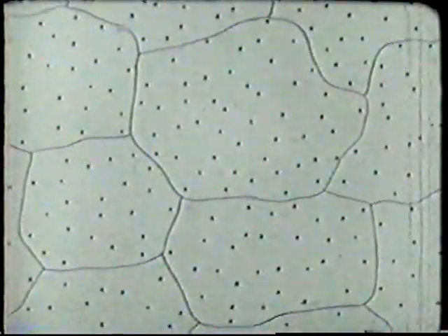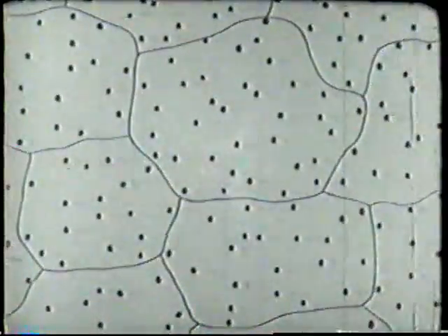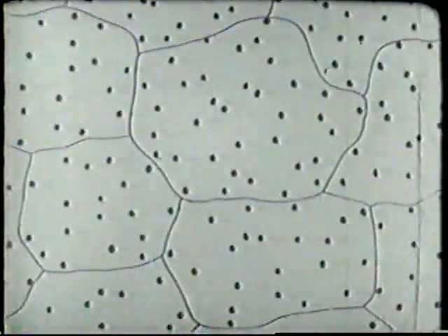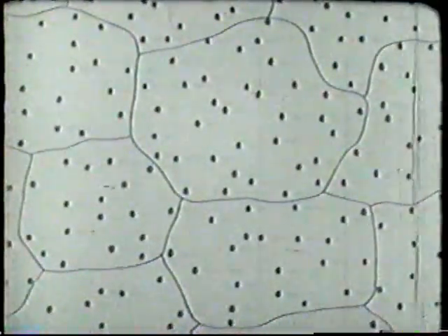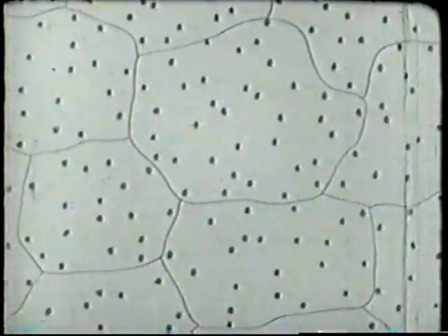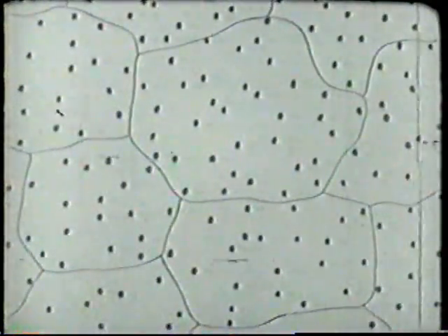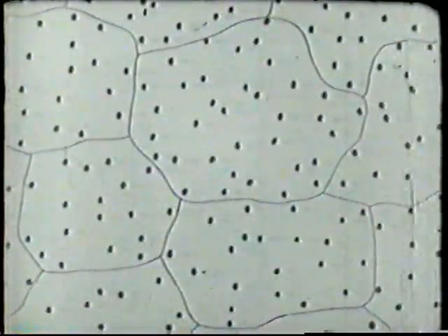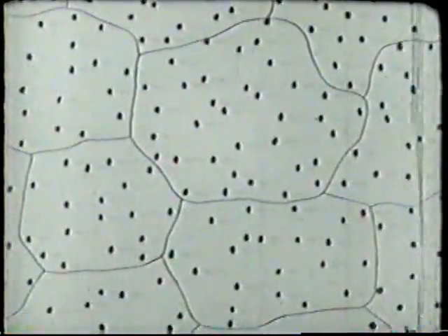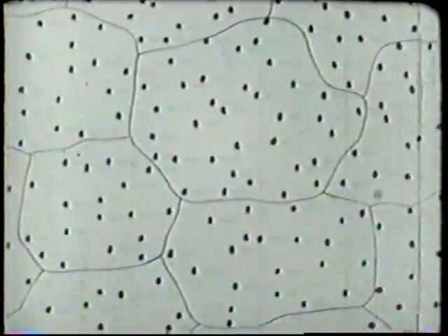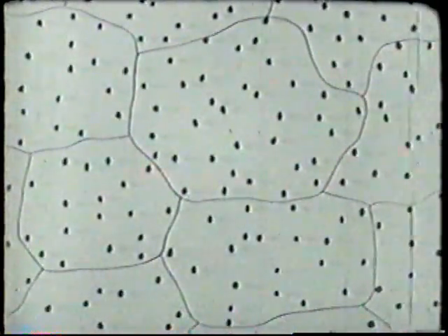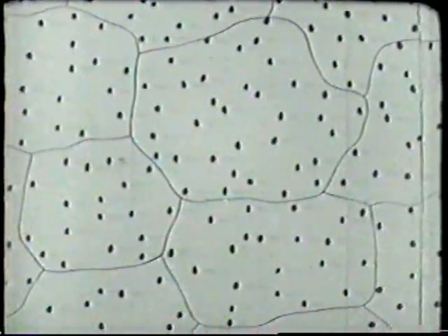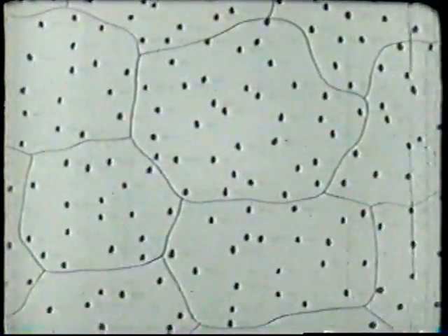In the annealing of a heat-treated alloy, the metal is heated at temperatures below the heat-treating range. The effect is to increase and accelerate the precipitation of this copper-aluminum compound from solution in coarse particles. This reduces the strengthening effect of the previous heat treatment. The alloy is now in its annealed or soft condition.